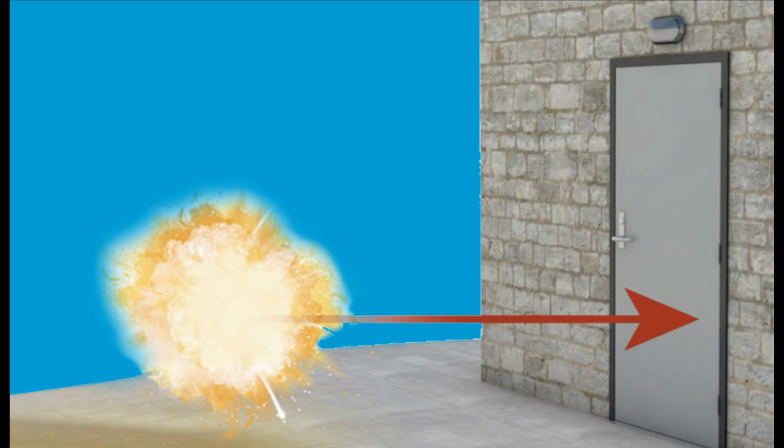I mean, 100%. We're not going to try to reuse the fire door after the event. Exactly. Got it. So you've got to get through that first. Once you have that identified, then it's how much blast are we protecting against? Is there rebound, duration, impulse? I can throw all kinds of fancy terms at you, but if the architect doesn't know any of that information, then we can start qualifying. Right.